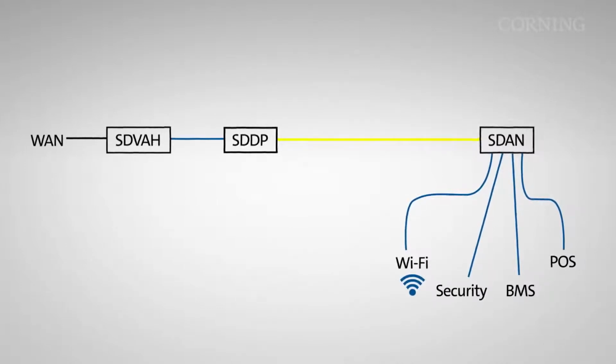Along the way in the IDF closet, we're going to be injecting power. So this entire facility has centralized power. The power is going to be coming from the MDF or the IDF locations. We're going to inject power into composite cable. Composite cable has both fiber for connectivity as well as power to power that end device, which is the ONT.